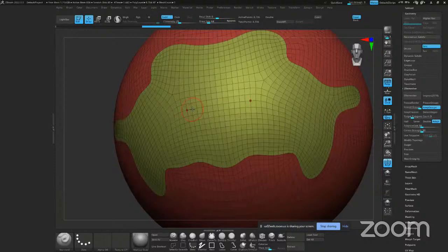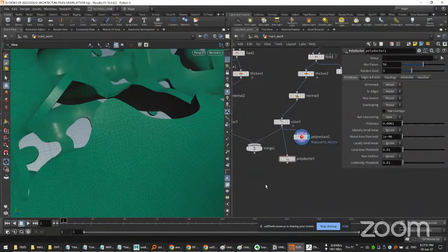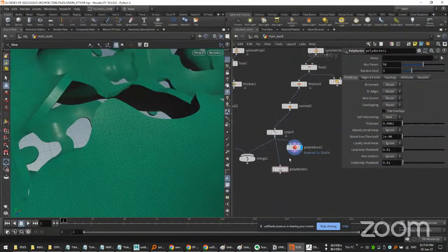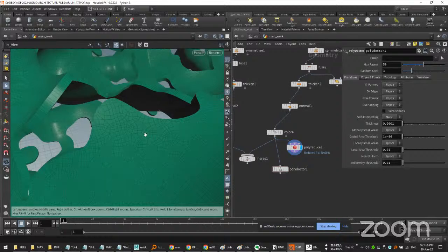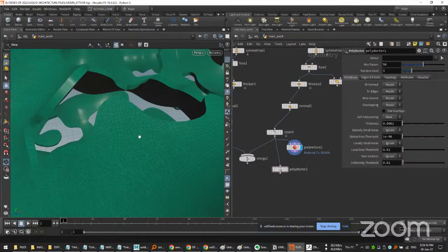Yeah, you can even retopologize there manually if you want. But it will take time. For example, if you want to retopologize something in ZBrush by using the manual option, it will take a lot of time. So ZBrush is pretty nice when you're working with just one object. But if you're working procedurally, I mean, if you want to obtain several outputs, probably ZBrush won't be enough, because in ZBrush you need to work manually.